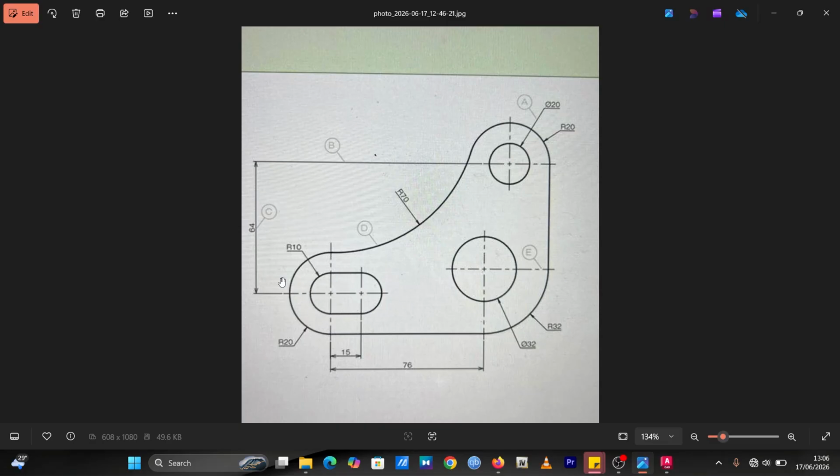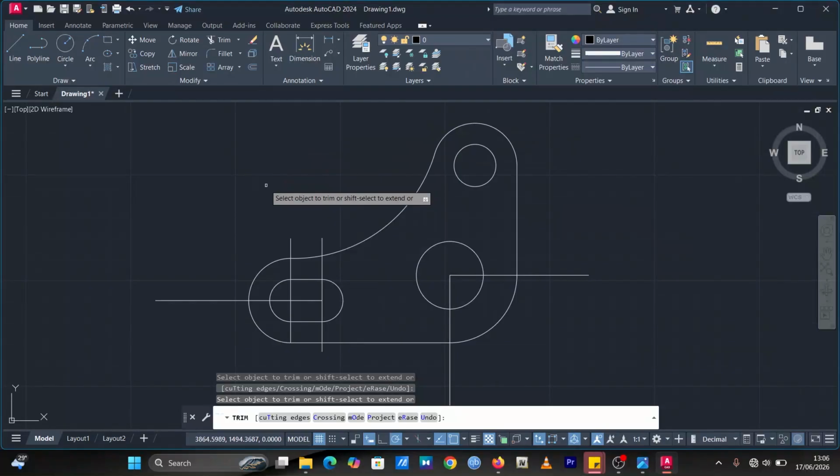So we are technically done with our drawings, but center lines are indicated with broken center lines: long, short, long, short. So we are going to do that, and after that we do the dimensioning, and we are done with our drawing. So to not erase everything and make your work look irregular or have any issues with your work,